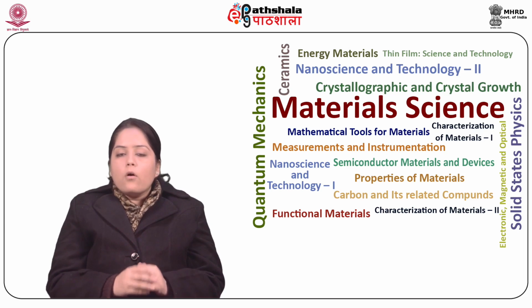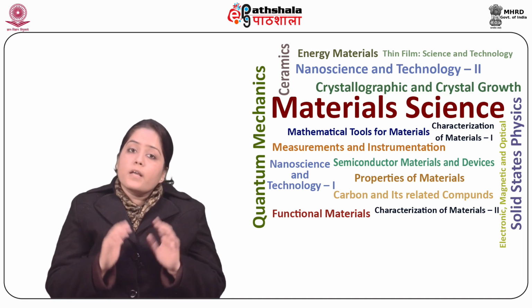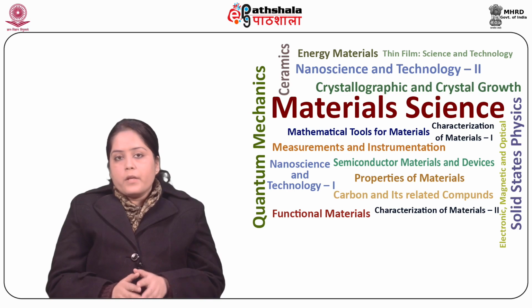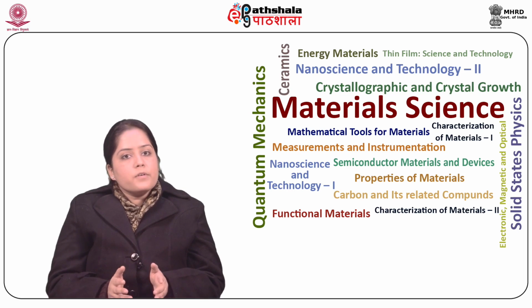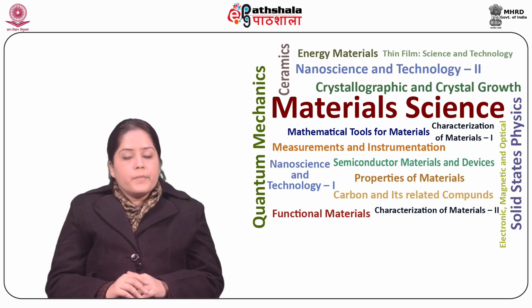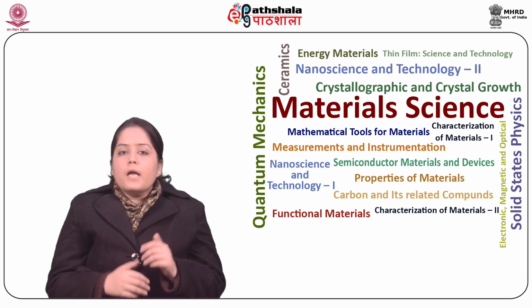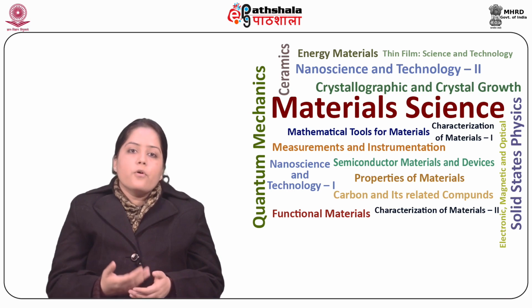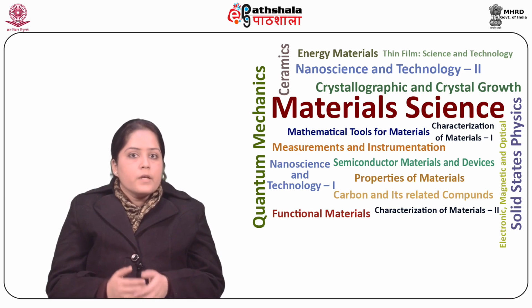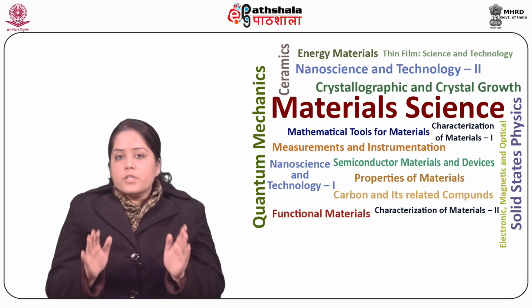However, the non-aqueous RFBs utilize organic electrolytes that offer a significantly wider electrochemical window, for example, above 5 volts, and larger solubility for redox compounds, thus providing a larger value of energy density.